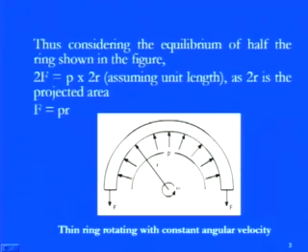Now, by considering this particular figure, as I told you, we have this thin cylinder or the rotating ring. This is rotating, and we have a centrifugal center. Since it is rotating at omega, whatever forces are coming will be m omega square into r, which gives a pressure. Then we consider the equilibrium portion, because we have a symmetric section. So, we are simply cutting the portion.